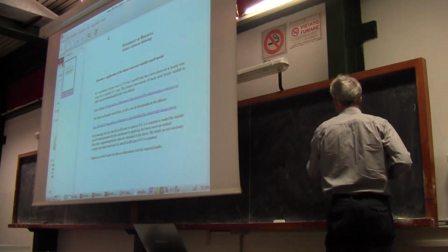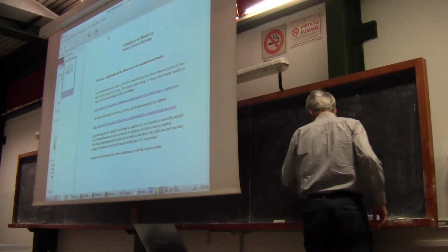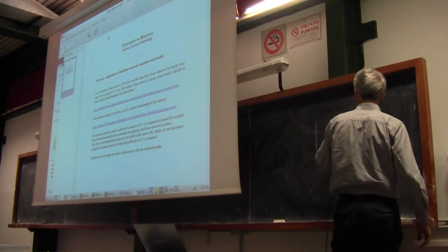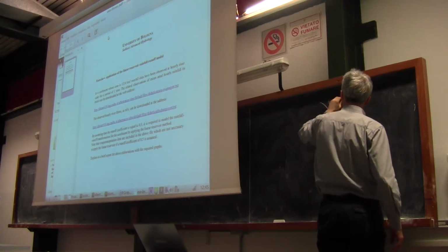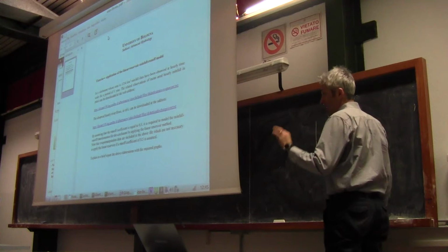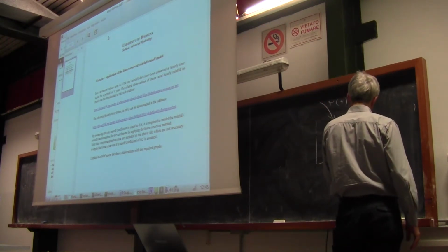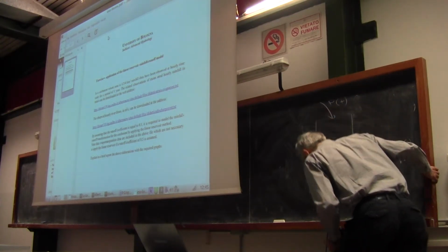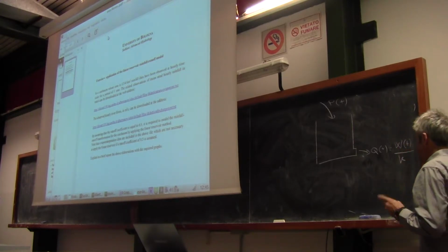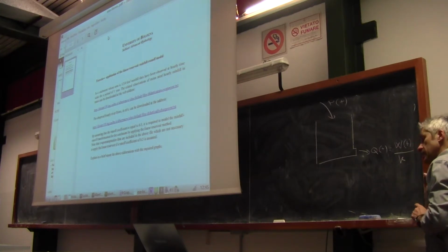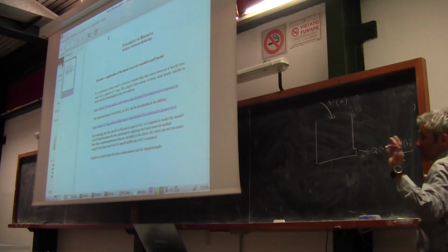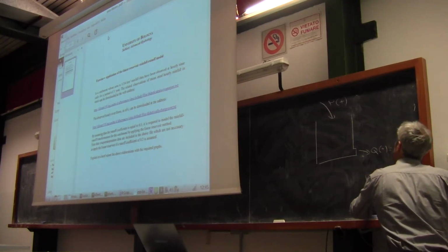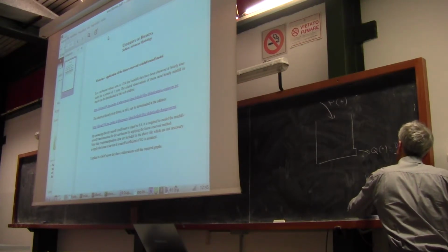What you need to do is, in R, it's very simple, but let's clarify it. Linear reservoir, it's a bucket model, as you remember, which means that you have rainfall, which you know, going into it, for hourly rainfall for 1 year, and you have river flow out of the bottom discharge, which is equal to, remember, storage divided by a constant. So first of all, you need to fix a value for the constant. And a value for the constant could be something like, by guess, you need to guess it. But I give you an order of magnitude. The order of magnitude could be something like 50,000.